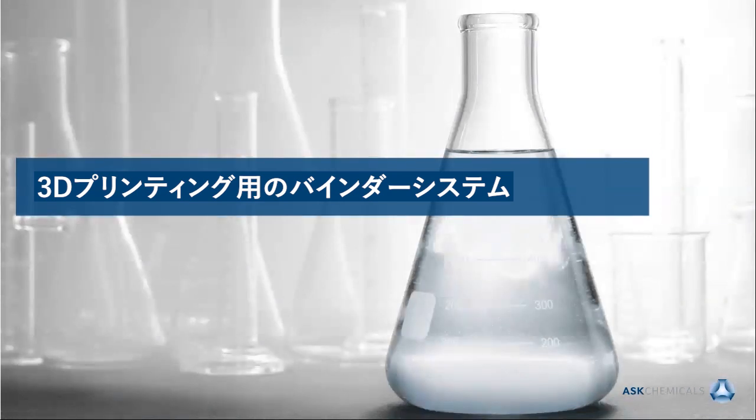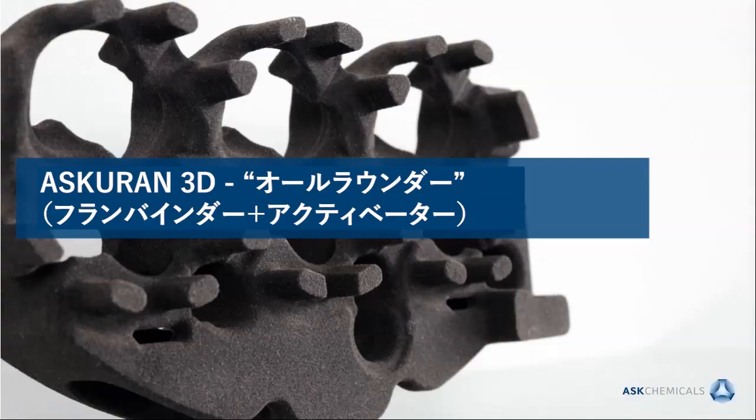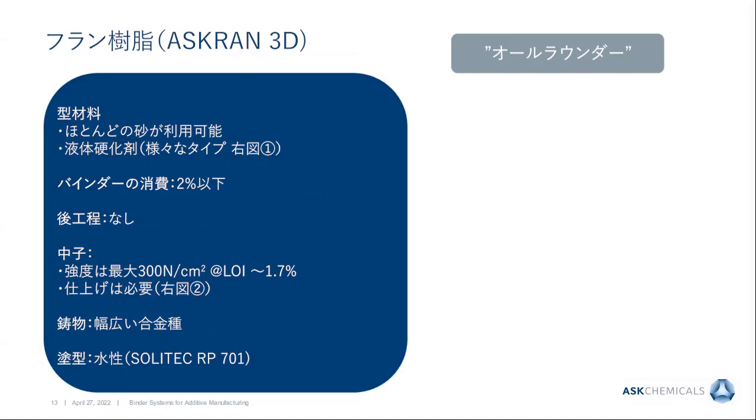So let's have a more detailed look into the printing systems provided by ASK. And let's start with Ascoran 3D, which is a furane binding system combined with a liquid activator in the sand. So in terms of the molding mixture, most sand types are applicable with this system. And as already mentioned, there is a liquid hardener which can vary in type, and the variation in type already gives one the possibility to steer the process in terms of reactivity.